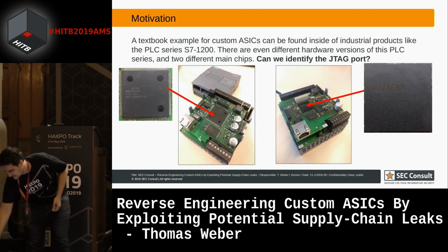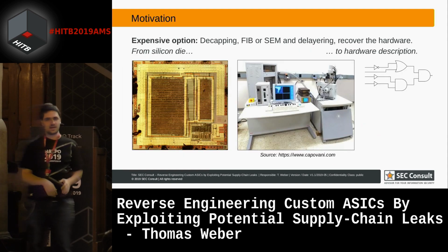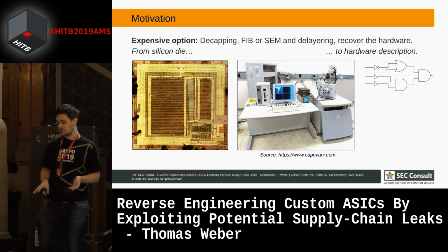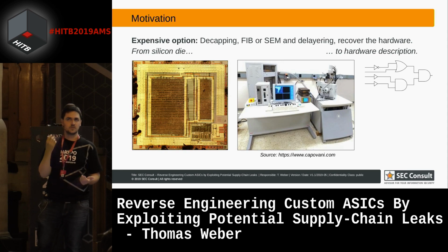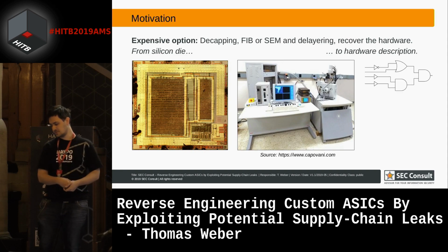Can I identify some debug port or anything else? The expensive option would be decapping, looking into the 10, 20, 30 nanometer structures, making pictures and doing reverse engineering of that. For that you need electron microscopes, focused ion beam stations, and so on, and a lot of time.